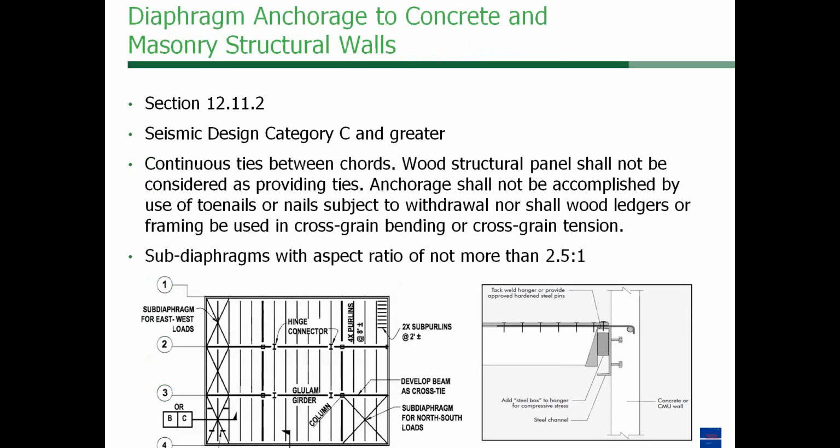And finally, for diaphragm anchorage to concrete and masonry structural walls, if there's a case where you have a wood frame diaphragm anchored to concrete or masonry, you have provisions that have been in the code for some time to make sure the wood diaphragm is properly tied to the concrete or masonry wall to avoid a failure of the diaphragm.